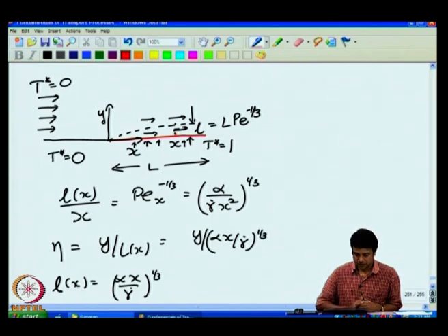Okay. Therefore, the temperature field at that location should depend only upon the distance x from the upstream end of the heated section and not on the total length L. I have neglected in this case streamwise diffusion.